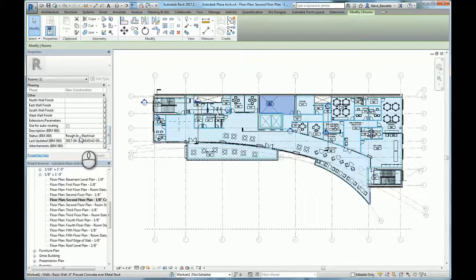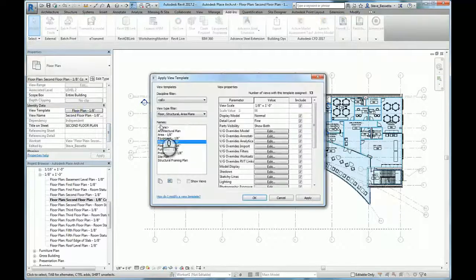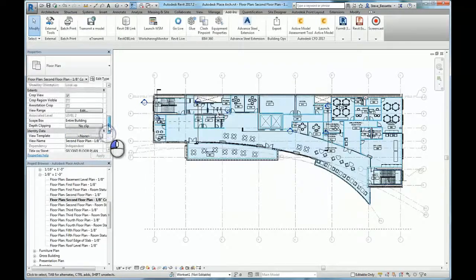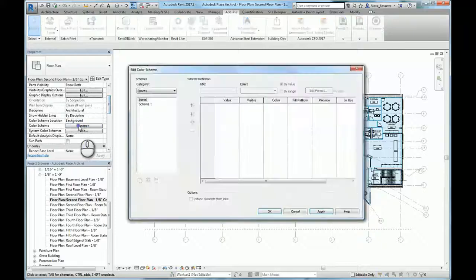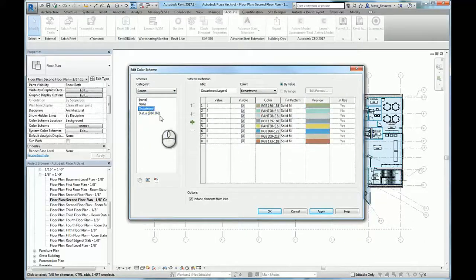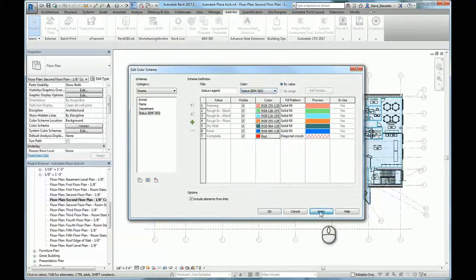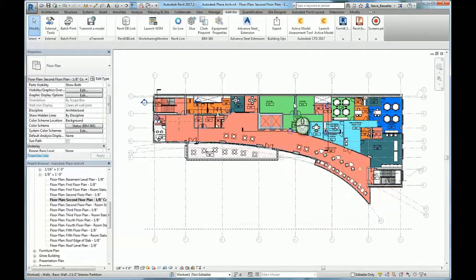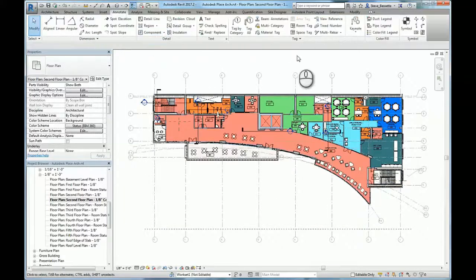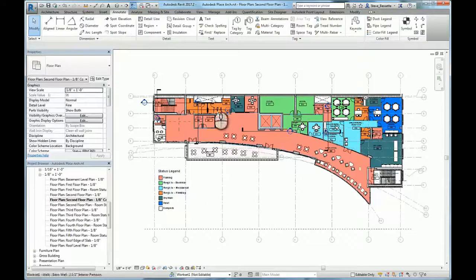Absolutely. And I think this is a perfect way to highlight the connectivity, to do things like run analysis of where I'm at on any given floor plan, any given level on my project, right? I mean, we talk about Excel spreadsheets early on, and oftentimes this is the way it's tracked in industry today as far as the closeout status of a room. And that can just be, frankly, hard to track, hard to reflect. There's no graphic tie to that line item. So I think what you've done here, which is in the Revit model, basically applying a color overlay, a filter onto the floor plan, and then you're able to actually see that status depending on where you're at.